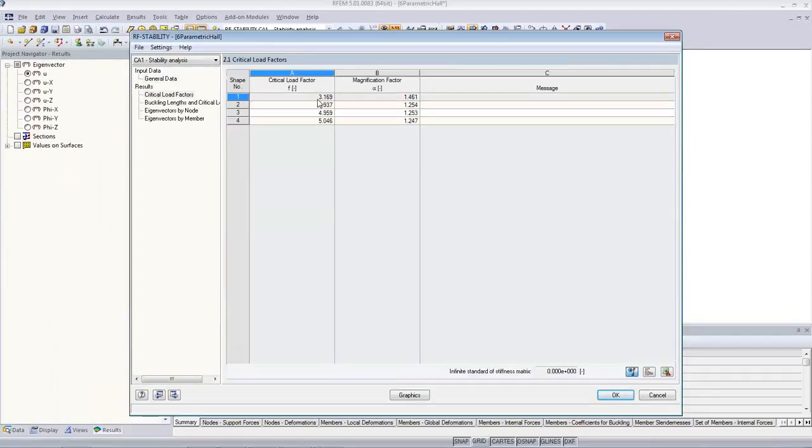That was the basis of my analysis, and I can basically linearly extrapolate it 3 times 169 times the load on this structure that I have now in order to be stable. This is one number that shows me how far I am away from instability, from the point of instability.